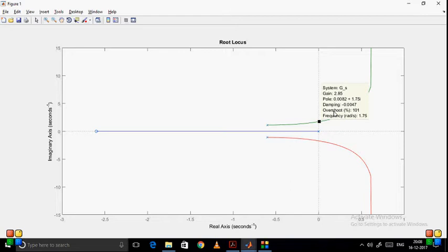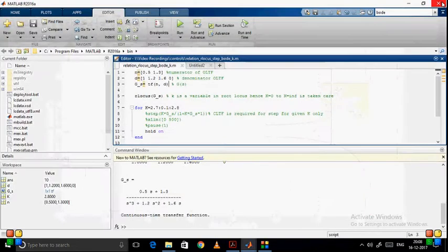Now this is our understanding in root locus. So let me close this. Now I just want to understand the same thing with time domain analysis. For that I will comment this out. I don't want to see my root locus, but I should know that at 2.7 the system is stable and at 2.8 the system is unstable. Now I am plotting two values, K equal to 2.7 and 2.8, with an increment of 0.1. I just need two graphs, so I don't want to confuse too many things.